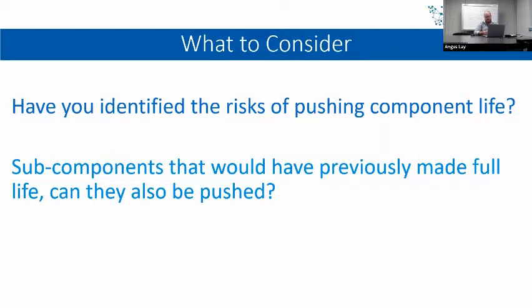But if there's still life left in that component, then there's the proof or the evidence or the data to indicate that you can safely push that component. And again, if you've got a component that has failed in service or didn't reach target life, it's critical to get those teardown reports done to understand what caused that failure, so you can put steps in place to mitigate those risks. Otherwise, you're just going to continue to potentially repeat that issue.